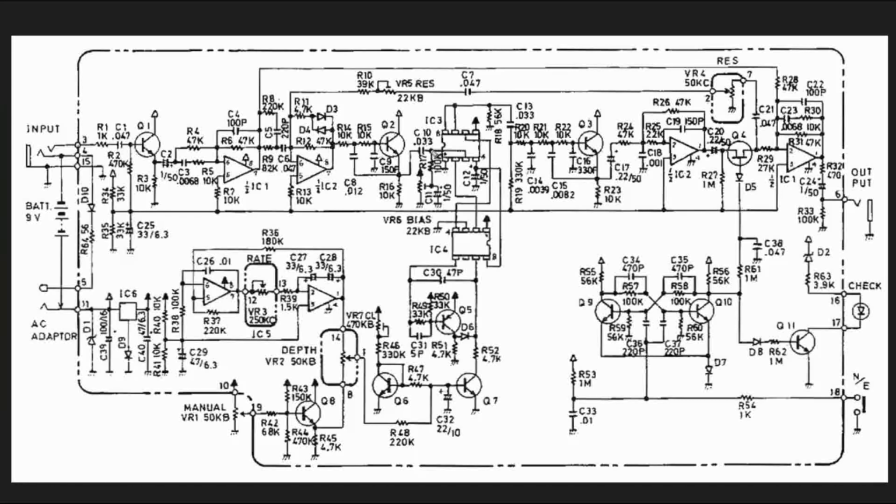But that first difference, where you have a super short delay time that you're modulating, results in an effect that we call comb filtering. Now, there are lots of different kinds of filters out there. We have low-pass filters, we have high-pass filters, we have notch filters, and we have bandpass filters as kind of our four basic types of filters.